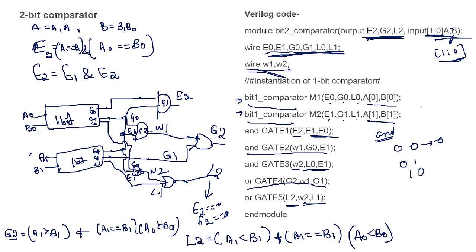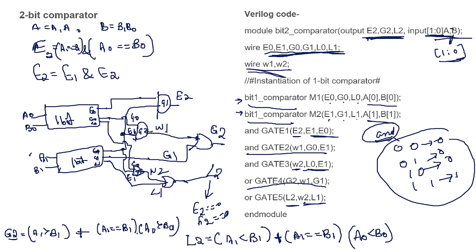This complete truth table is defined in the Verilog library itself, so if you instantiate this AND directly, you get this truth table. The other method is user defined primitives, where as a user we can define, for example, a gate having the same truth table as an AND gate. That is when we use user defined primitives.